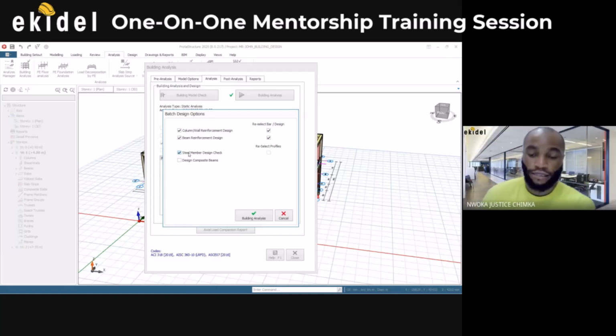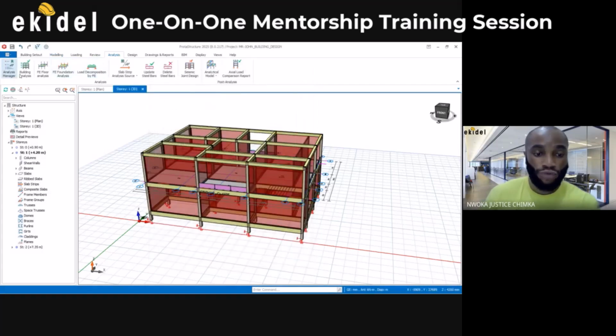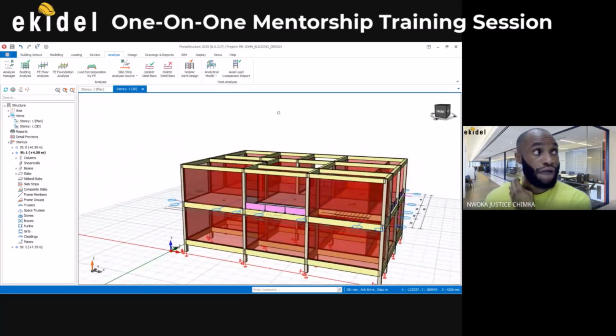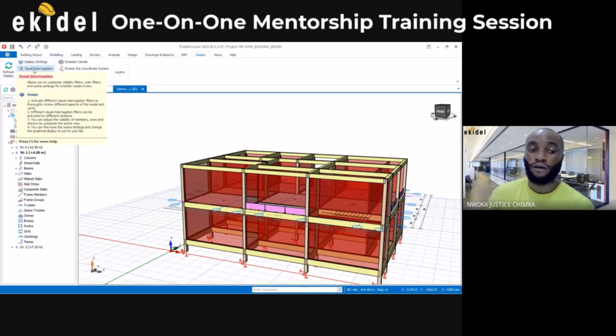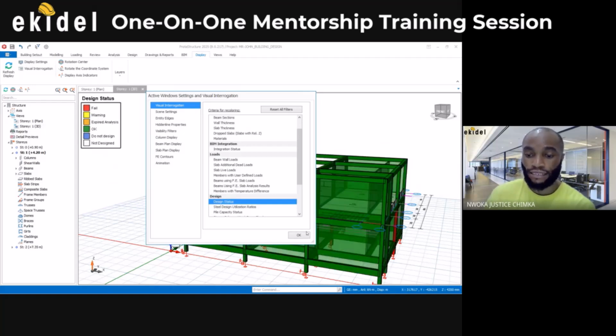All right. Exactly. So let me just cancel now and then close. In this case, you can see that this is not ticked. We have performed the building design for this building. Then to see the members that are failing and the ones that are having issues, you come to this place that says Display. On our display tab, you will see Visual Interrogation. Then click on this place here, and then scroll down to design. You can see design here. Then click on design status. You click on this now and then say okay.